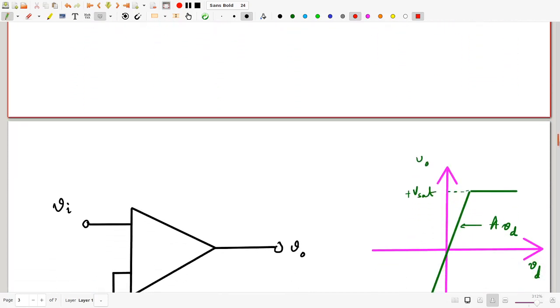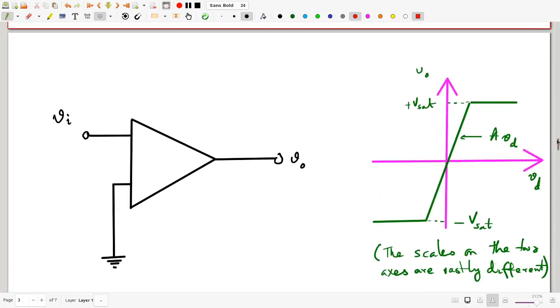Okay, so now let's consider a very simple circuit, the simplest possible op-amp circuit, where you just have two inputs, one output of course, but you have actually made life simpler for yourselves by grounding one of the inputs. By the way, the standard convention is, if the inputs are not labeled, then the one on top is always taken to be minus, the inverting input.